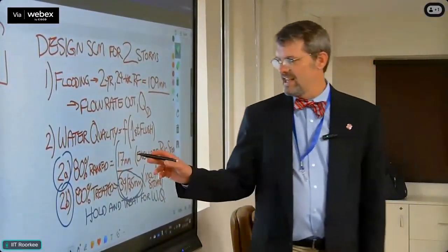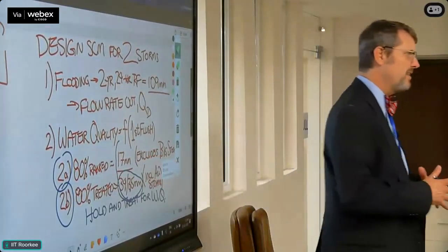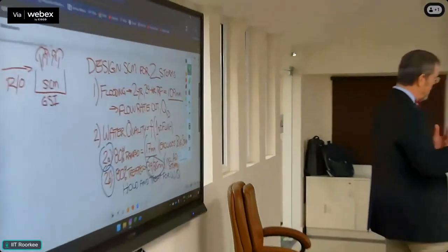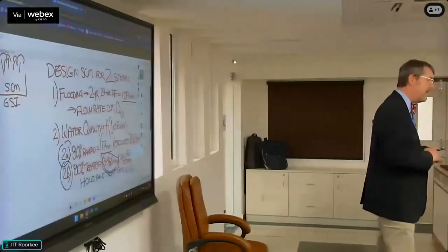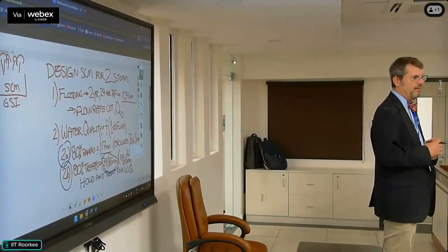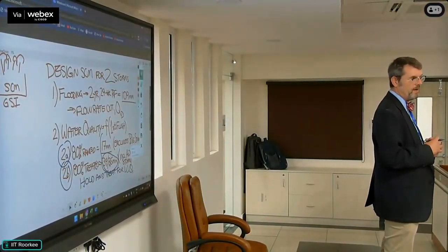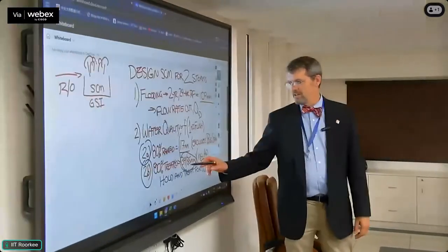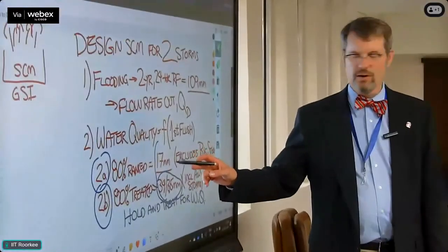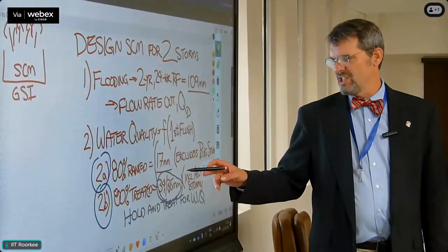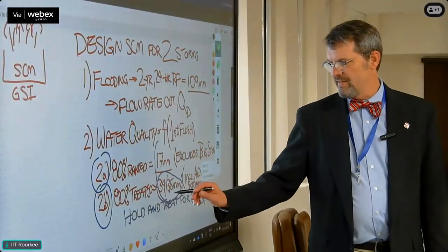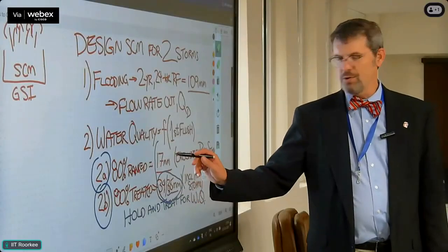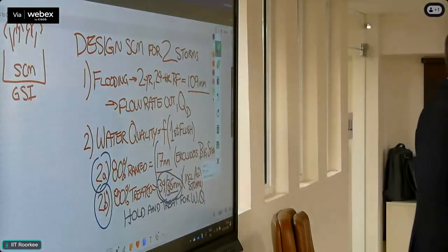If you went with 17 millimeters, that's not a very careful number. That's not a cautious number. But it may be the financially acceptable number, all right? Because your practice is literally going to be twice as big with this number compared to that. If you're asking a stormwater control measure to capture 35 millimeters, that's twice as much as 17 millimeters.